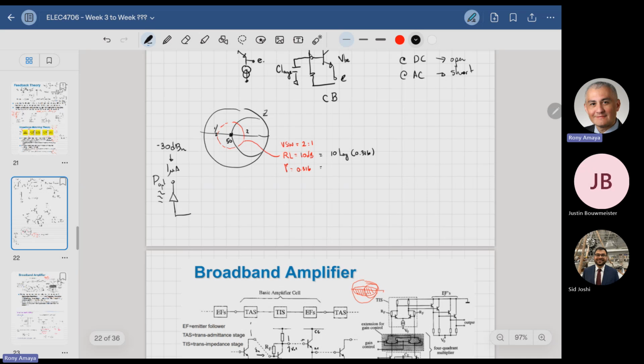And this is actually used in something called a PON, which is a passive optical network. It's effectively a transmitter that goes into multiple receivers down into the metro area, and you're basically getting one of them. And you don't know if you're going to get plus 20 or minus 30. The losses are all over the place. But you got minus 30 dBm coming in, worst case.